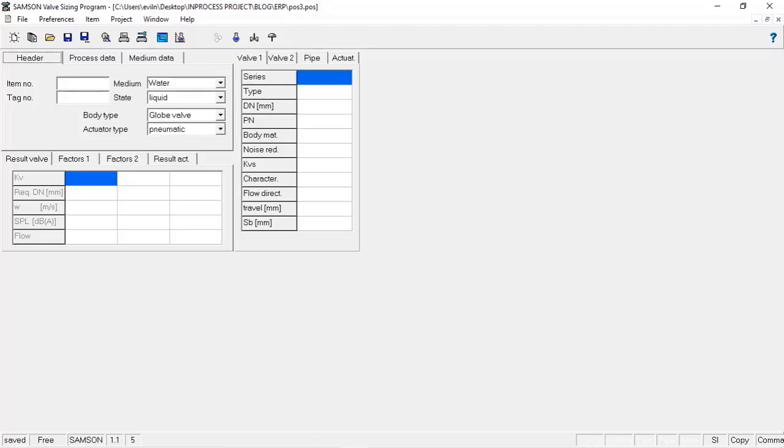So if you have pre-selected your control valve, it will help you to get costs and so on. Moreover, we can verify if the control valve is able to work in the range of operations that we need, or if we will need to consider more advanced control strategy like split range and so on.